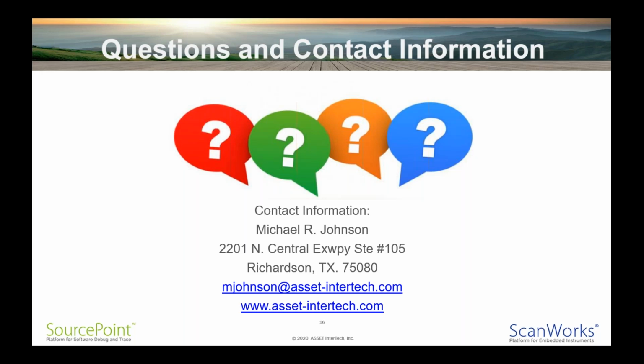Okay, thank you, Heidi, for that question. If you're just starting, you'll first need to create a ScanWorks project and a design, as you normally would. We've got our ScanWorks users on the line. You know how to create a project and a design. So you would start out there as normal. Then you would import the chiplet BSDLs and the netlists. Again, the same steps that you would take in your normal ScanWorks project development flow.